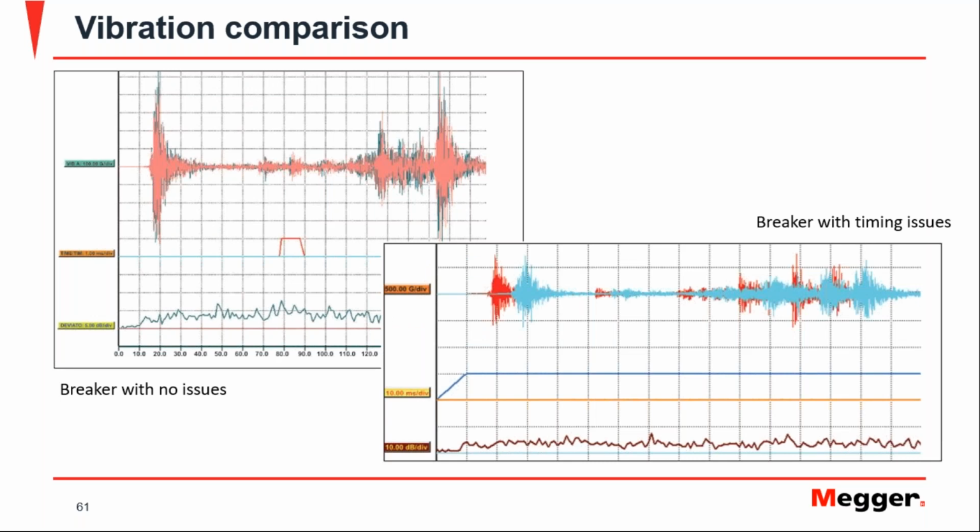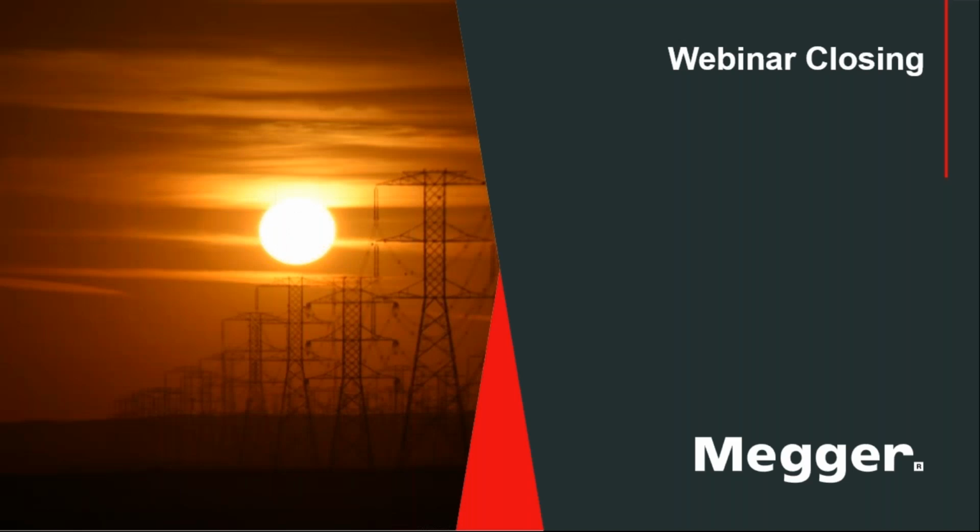So the mechanical events are happening differently, and you are looking to compare the difference in time and in magnitude of the vibrations to start analyzing the breaker. As I said, the analysis is not so straightforward. As with any fingerprint signal, you need to understand what's going on, and where you are getting this vibration from.